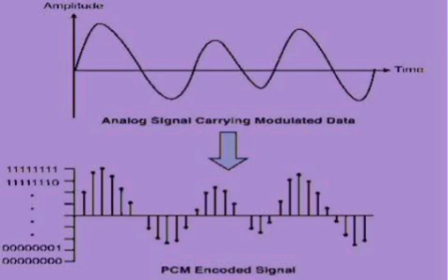Now comes pulse modulation techniques. Pulse analog modulation techniques are of three types, namely PAM, PWM, and PPM. PAM: in this modulation scheme, the amplitude of a high frequency carrier is varied in accordance with the sample values of the message signal.